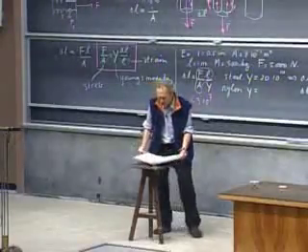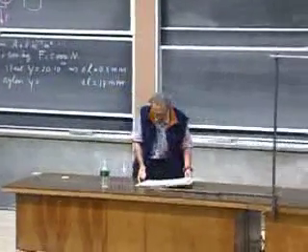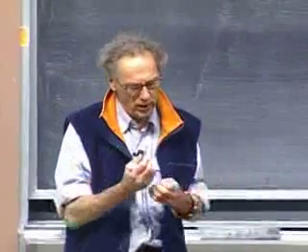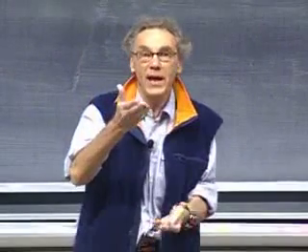Now, before it breaks, we reach a situation that the strain is no longer proportional to the stress. In other words, we abandon Hooke's law, as I will show you also today with a demonstration. The material begins to deform. It begins to flow in a way. And even when you take the weights off, it will no longer have its original length. It will not return to the original length, but it will be much longer.